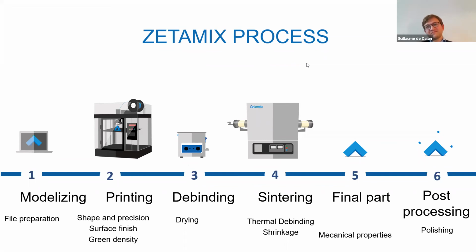The big issue will be sintering. It's easy to print. For instance, we could print a part in ceramic and a part in metal, which would be really nice in terms of, for instance, electrical properties. You would have an insulating part and a conductive part. So that has some obvious application and interest. You can print it, no problem. But then it goes to sintering, and managing to sinter two materials together is a complex bit of science. So for the moment, we kind of stay away from that.